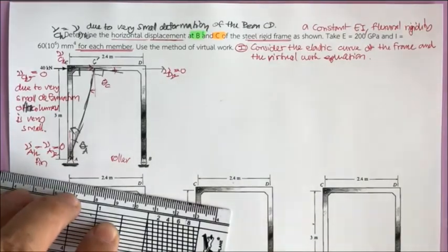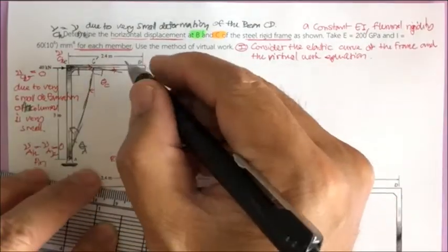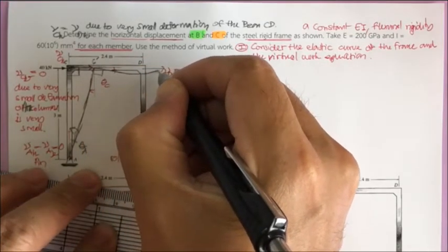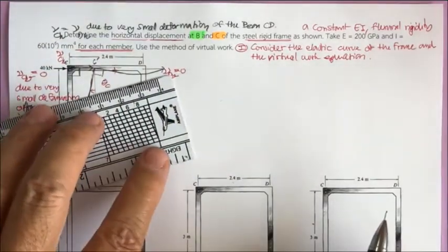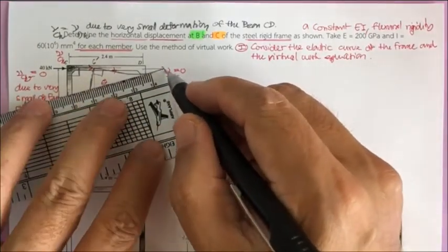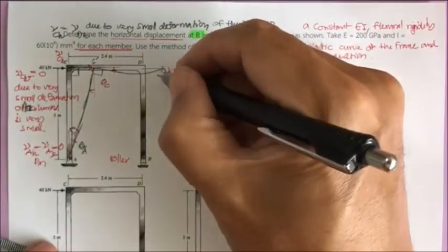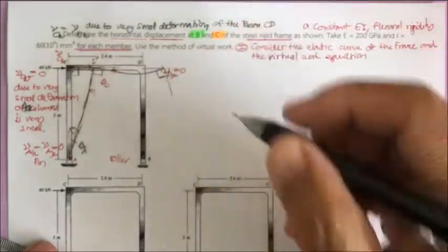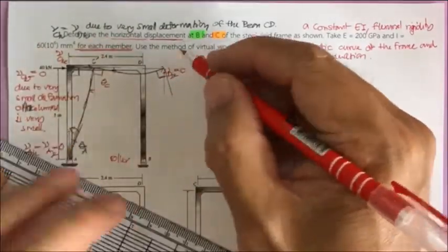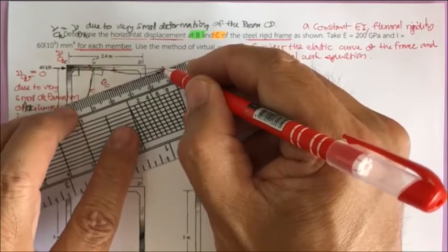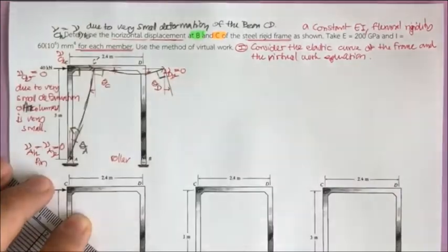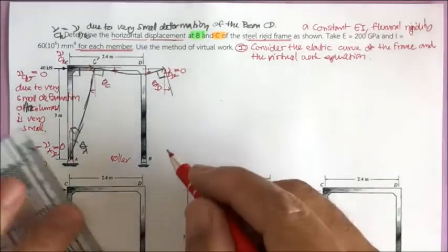And if this occurs, what is going to be the rotation over here? Yes, over here the frame is going to bend from here to here. Again, the angle at this joint will be maintained as a perpendicular angle, so this must be like this. And the rotation here, from here to here, is going to be theta sub D, as the unknown.